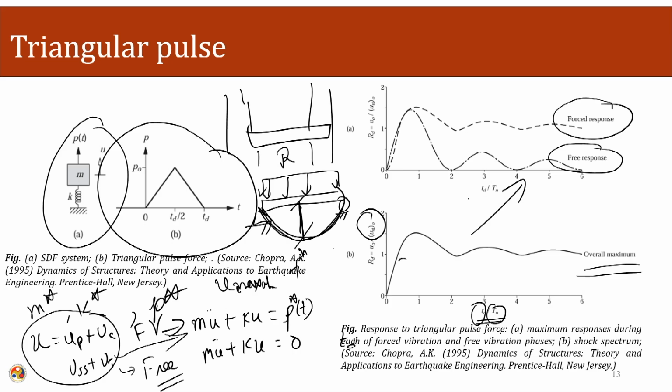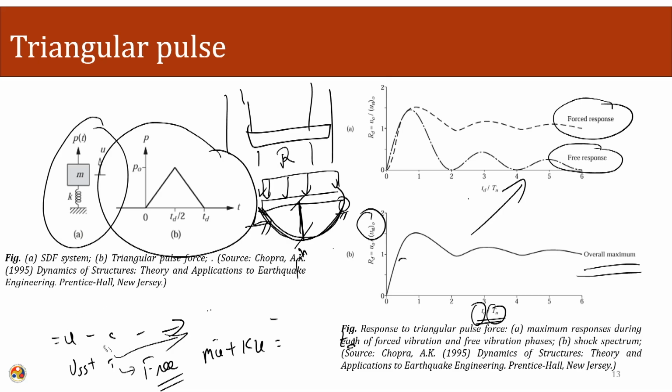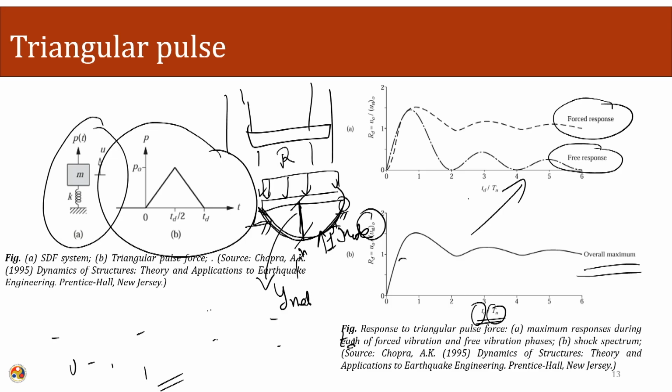Here one thing which needs to be noticed is that in this particular treatment we have chosen the first mode and the deflection y max at the center, because for this particular case, let us say we are showing this for a simply supported case loaded with a planar condition.